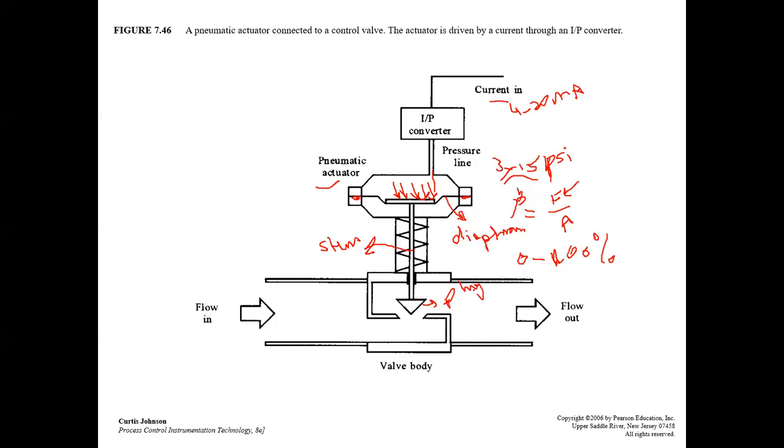It is a proportional valve, not like an on-off valve. An on-off valve is only either fully open or fully closed. And we have, okay, this is the valve body, and in this example diagram, this control valve is a normally open valve, because we apply the pressure from the top here to close it. So it is normally open. When we apply pressure, we will close it.